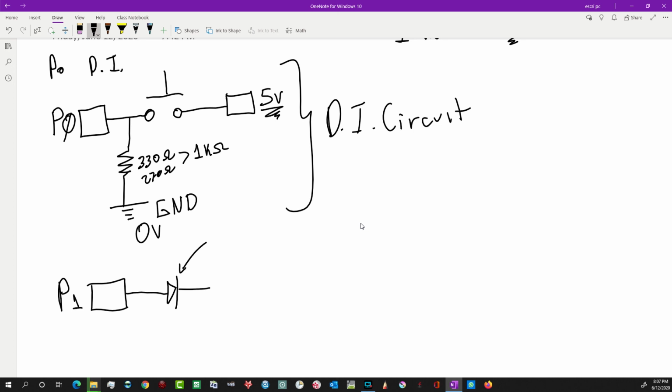So this has to be connected to 0 volts, because my port is going to produce 0 volts if I have a low value or a negative value on my digital output. And so 0 volts and 0 volts, there is no voltage, there is no force to move the electrons, and the LED is not going to turn on.